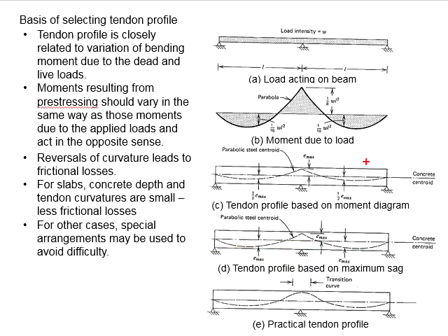It was mentioned that sudden changes in the curvature will lead to significant frictional loss. In order to prevent excessive frictional loss, normally we make the turnings smoother, and there will be a transition of the curve so that the gradient will later be adjusted to the intended gradient in accordance with the tendon profile.